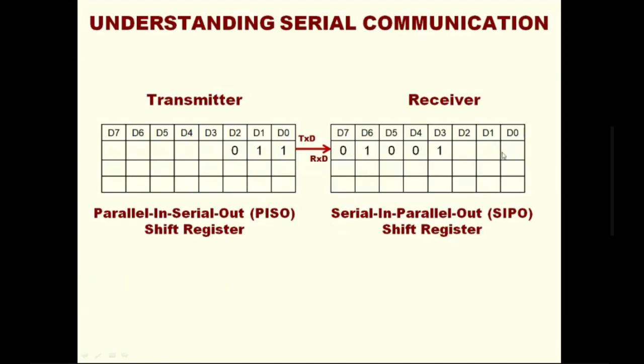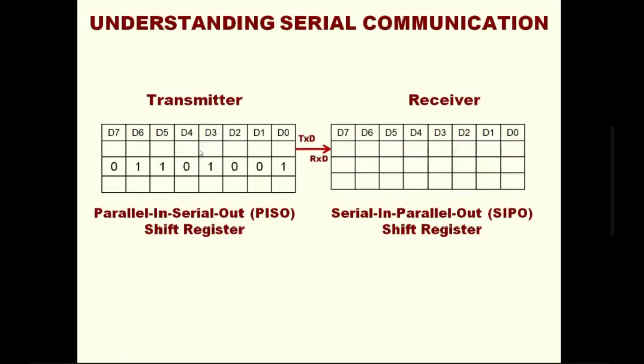transmitted, and the receiver will receive the first 5 bits of the first byte and the LSB 3 bits of the second byte, and it will consider that as 1 byte. So this is a big disaster in serial communication. To ensure all the 8 bits are shifted out and the transmitter is empty, only then we have to put the data once again in the transmitter side.